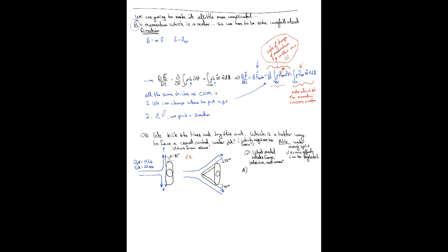It says that the sum of our forces is equal to d/dt of the integral over the control volume of rho V_xyz dV plus the integral over the control surface of rho V_xyz (W dot n hat) dA. And now we have some decisions to make.